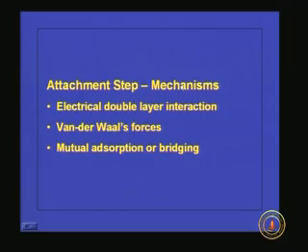There may be a streaming potential developed across the filter. Because of this streaming potential, the filter particles will have a potential difference between the top and the bottom. That means the filter media at the top may have a high negative charge compared to the bottom one. The bottom one will have a high positive charge compared to the top one. Similarly, the particulate matter present in the system will have the charge the other way. So, because of that there are chances of particles getting attached.